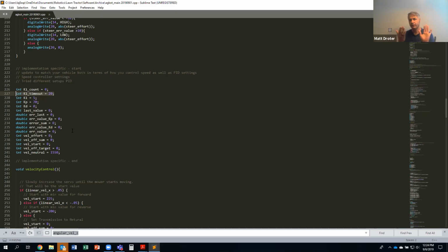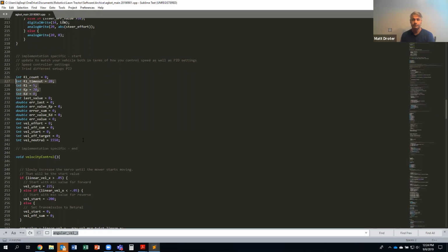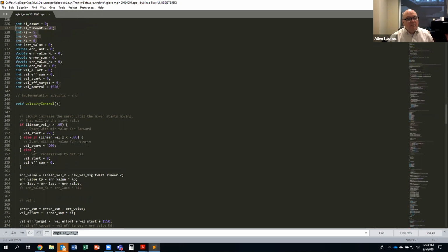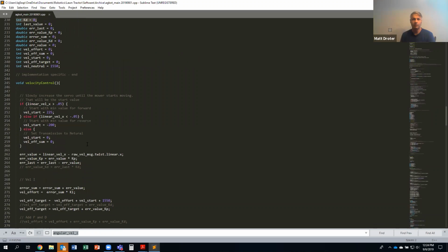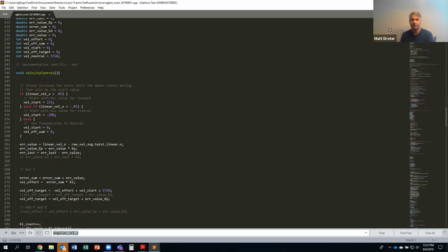We had to find the steer left, steer right, and steer center. When we first took it out, we tried to get it close to center when it was on blocks. When we drove it, it was bending to the left a little bit, so you got to adjust the center point. But after that, we just drove it around. But you kept the PID settings. Yeah, surprisingly. Okay, no reason to break that mold. You may get different mileage on it.